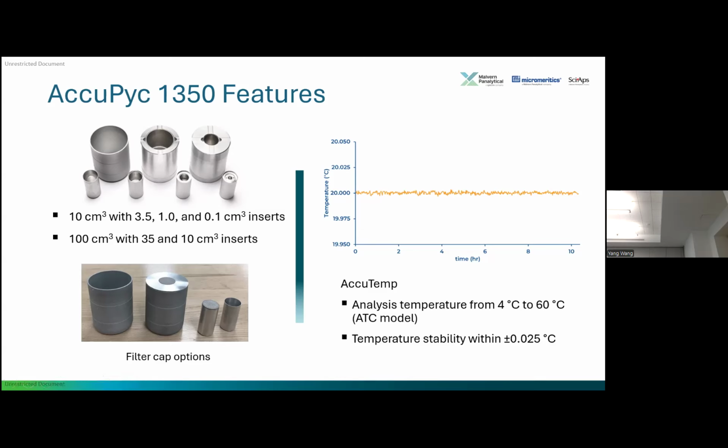Also, one of the critical things when you're determining volume from gas pycnometry is temperature. You have to control the temperature, or at least take temperature into account, because if temperature changes slightly, the pressure will change for the same quantity of gas. And the only thing we're measuring in the instrument itself is pressure. So if the temperature is changing, you're reducing the resolution of the measurement, because the pressure is going to have some fluctuation. And so controlling temperature is critical.